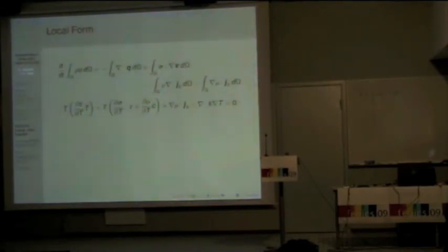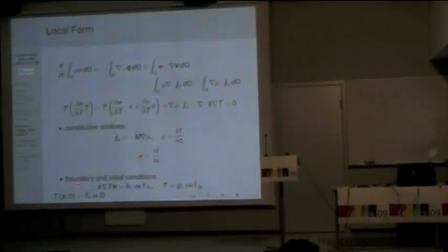The last equation is the balance of energy equation. This is its local form. It's not the usual heat equation, but a complete heat equation, in which we can see thermomechanical coupling and thermochemical coupling, which is here and here, and this is the classical Fourier law. These are the constitutive relations. I showed them before, so nothing new. And these are the boundary conditions and the initial condition.